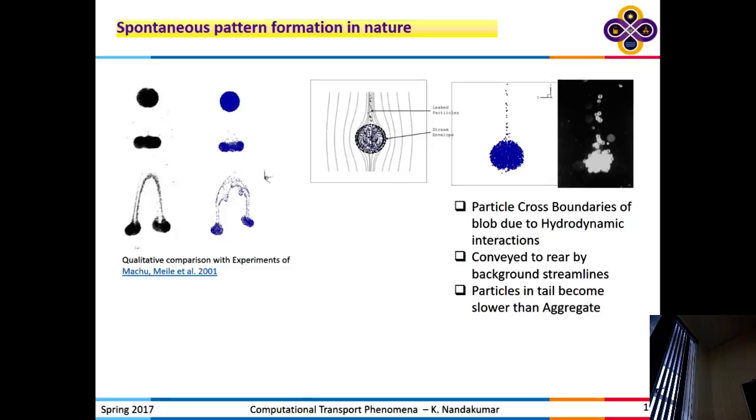Right? And this has been documented in the experiment, and using a certain modeling framework for multi-phase flow, we were able to do this. Now, interesting questions for project ideas for this course would be, what would happen if I have a suspension of droplets that are heavy, made of glass beads, and the other one that are light, made of polystyrene, for example, lower density than the liquid. I release the lighter ones from the bottom and the heavier ones from the top. And they're going to go like this. They're going to interact, and the particles will mix, and then they will separate.